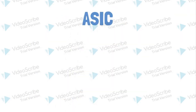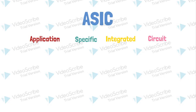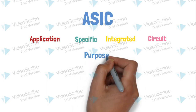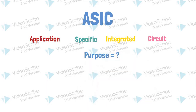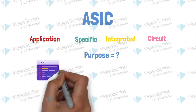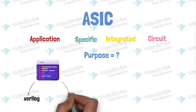ASIC, or Application-Specific Integrated Circuits, are chips that are built to achieve one specific function. Before you create a chip, you must know what the purpose of this chip is. And the way the chip's hardware behaves is abstracted using a coding-like language called RTL, such as Verilog or VHDL. This part of the design is called the front end.